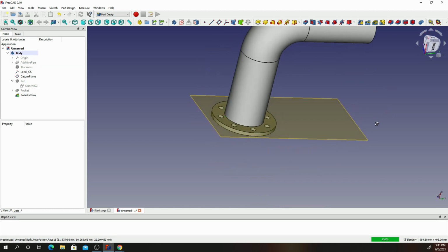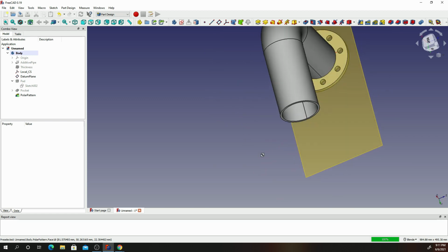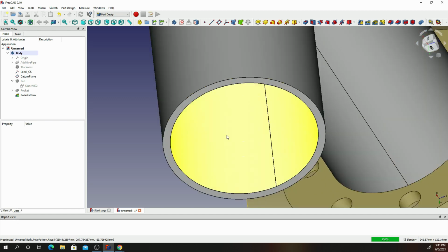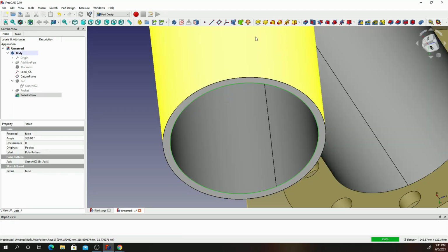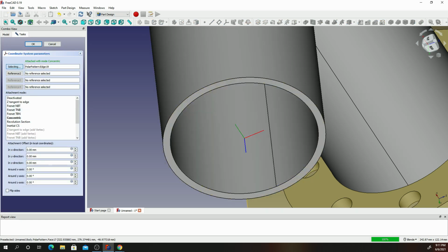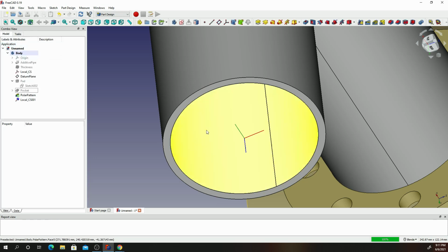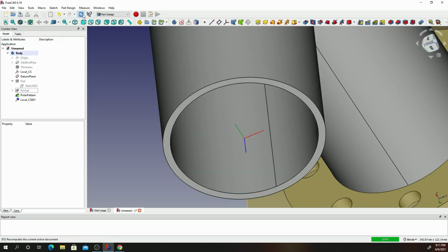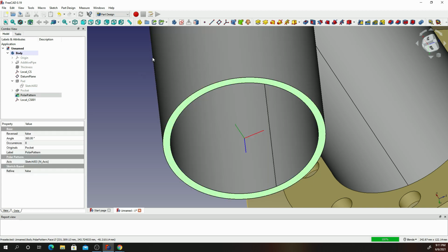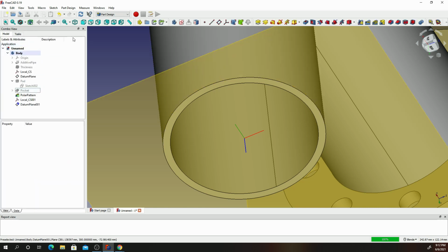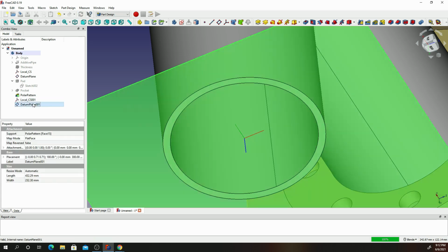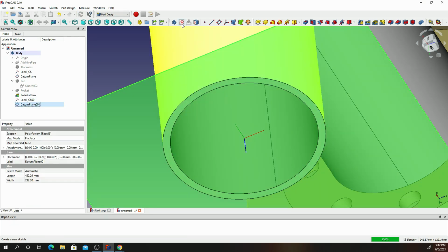Everything is fine, as you can see. So let's go ahead and draw the second side. Go ahead and click that second line. Click on create local coordinate. Click on selecting. Click on OK. Refresh. Click on that face. Click on create datum plane. Click on OK. Click on refresh. Go ahead and click on our datum and click on sketch.